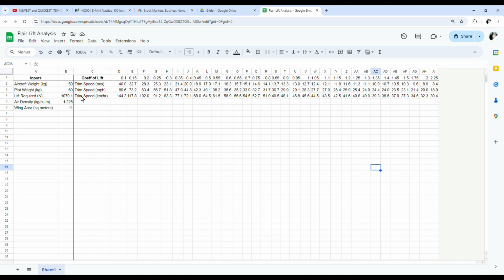So I'm using 50. Even if we took it down to 40, if I put 40 in here, it's not going to help that much. So you'd have to pull a CL of 2, which they couldn't do, not with that aircraft. We've seen the data now, and we know that the aircraft is going to be less capable than the section. The airfoil section will never pull a CL of 2. So even if the aircraft weighed 40 kilograms, you still can't get there.